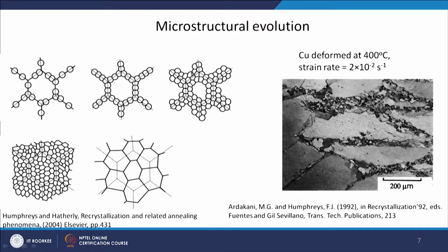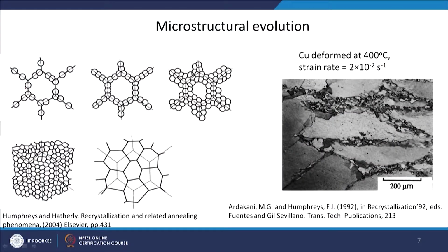So, sometimes it happens in high stacking fault energy materials also that you can have recrystallization, dynamic recrystallization instead of dynamic recovery. But those are very specific cases. Now, as I told you, let us look at the microstructural evolution in case of dynamic recrystallization. If you take a particular grain, this is the prior grain which was there before the deformation started.